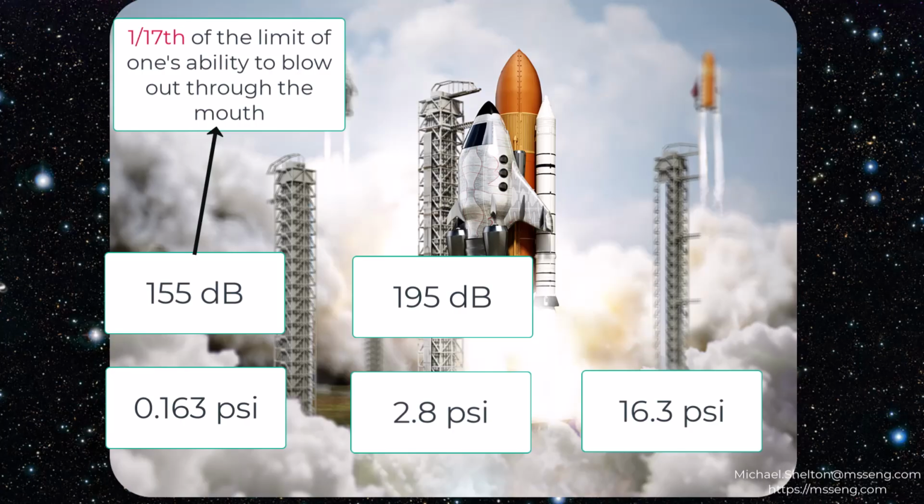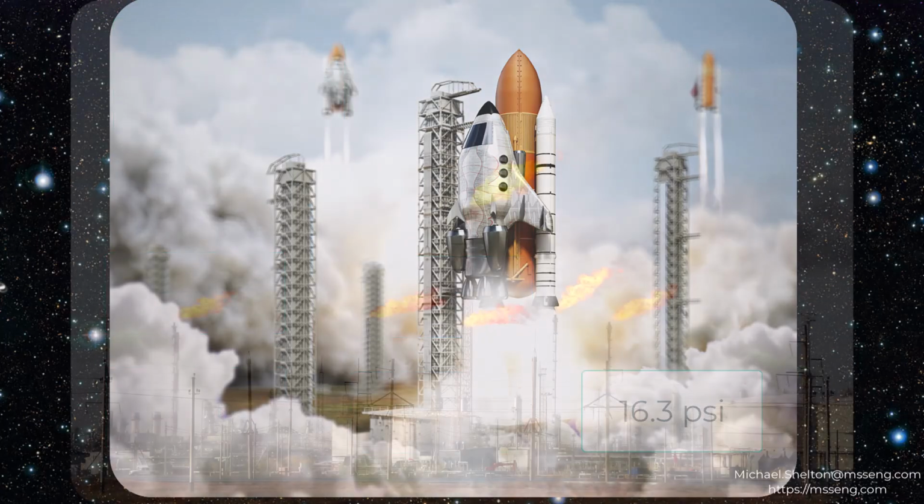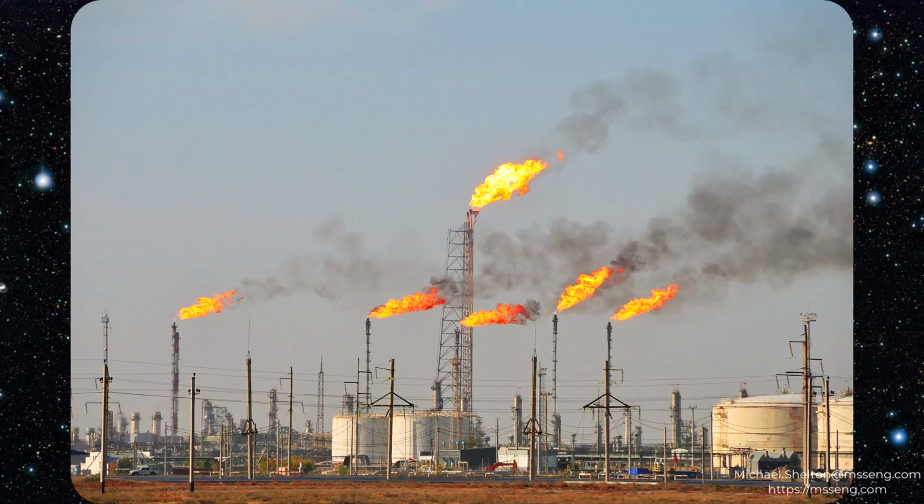Most AIV issues occur in plant relief systems. Since relief systems are normally used in plant emergencies, a catastrophic acoustic fatigue failure would present a serious issue, since the affected relief system may not be able to be shut down quickly. AIV is a serious issue.